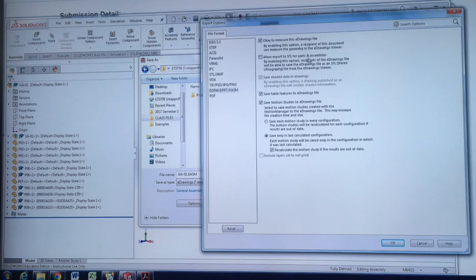By enabling this option, recipients of the eDrawings file will be able to save from the file. So that means that basically the 3D model that is contained in that file can be exported by someone else. An eDrawings file you can't typically open in another 3D modeling software, but if you're able to export an STL file, that STL file can be imported in different software. All right, so you're really giving someone control of your file if you do check that box.